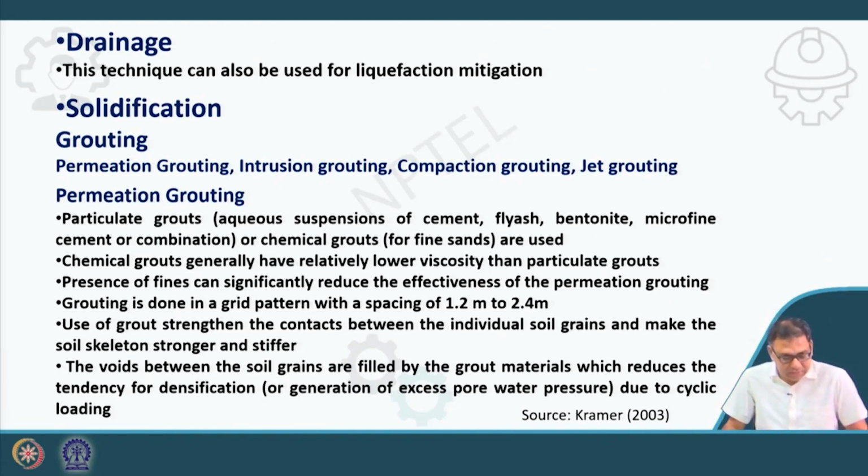The first one is the permeation grouting. So, particulate grouts, for example aqueous suspensions of cement, fly ash, bentonite, microfine cement or combinations, or chemical grout that is used for fine sand, are used.